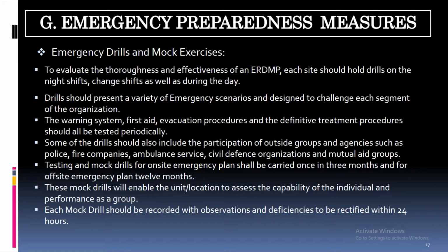Then drills should present a variety of emergency scenarios, which means these exercises should attempt to simulate as closely as possible a fire, explosion or toxic agent release, etc. Then the warning system, first aid, evacuation procedures and definitive treatment procedures should all be tested periodically. Some of the drills should also include the participation of outside groups and agencies such as police, fire companies, ambulance service, civil defense organizations and mutual aid groups.